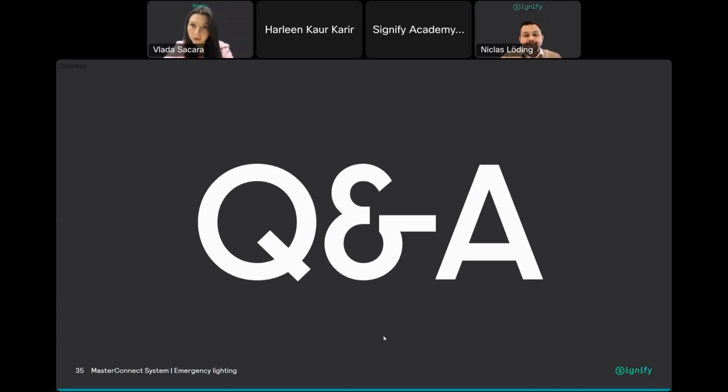Right, thank you. And then one on how many emergency luminaires we can have. Yes, in total, our networks can consist of 120 luminaires, and that can be 60 emergency and 60 normal luminaires, or 120 emergency and 120 normal. So basically, the maximum number of lights is 120 per group, and the split between regular and emergency can be defined individually according to the project needs. Thank you.